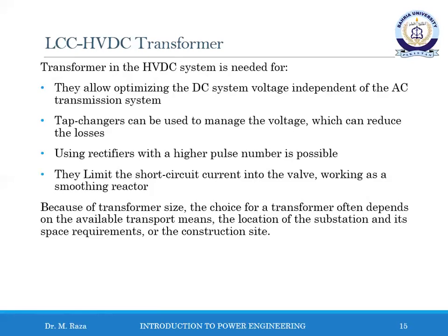There are several practical aspects of HVDC which cause the transformers to be more complicated, such as oversaturation of the core through DC current, higher test voltages, and specific arrangements to connect the windings.